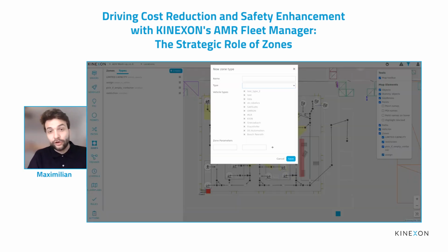The condition zone can not only be used for the detection of load carriers or for the replanning based on a sensor in the high rack, which space to take, but also for the traffic. You can, for example, say, okay, I have a condition. If a vehicle is in a certain area, please update your order and drive around. If you have 2 parallel hallways, usually the left way is always 5 meters shorter than the right way, so you go to the left way by default.